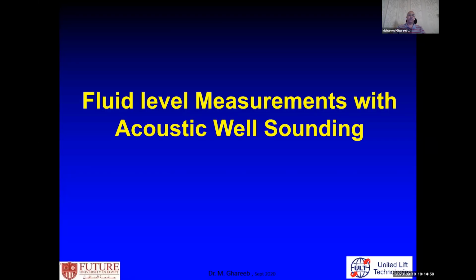Then one of the very important tools, as we said, is the dynamometer card. There are two dynamometer cards. One is measured and one is calculated. The measured one is the surface dynamometer card. It is a relationship between the fluid load and the position, and it's measured at the top of the polished rod, at the point where the polished rod connects to the pumping unit at the carrier part, at the connection point, and it uses what you call a load cell.